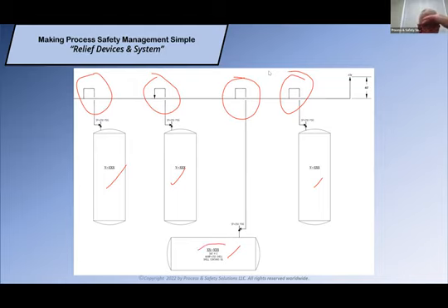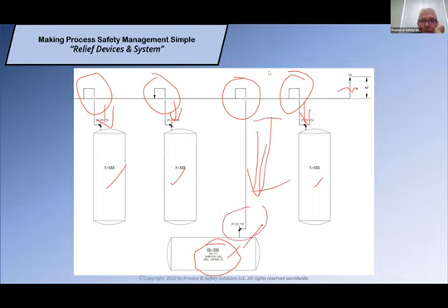But in this particular case, look at what's in here. I'm relieving the shell, which contains oil, into this header. Let's say this was a heat exchanger, and that's what I think we've tried to say here. If I relieve this, I relieve oil into this header. Eventually, as that oil builds up in there, I start overflowing oil down to each one of these. Not to mention, this is already full of oil. So the more head pressure this builds, the less likely that relief valve will lift when it's required to lift.